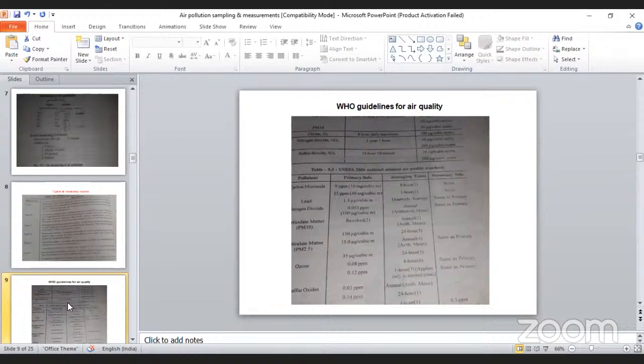Stack sampling is a kind of device where people use filter paper as a collection medium. When we are sucking the air from the atmosphere through the inlet manifold, they provide the vacuum. Under the vacuum, it is sucked and collected onto the filter paper. Then the filter paper is brought into the laboratory, where they do the analysis.